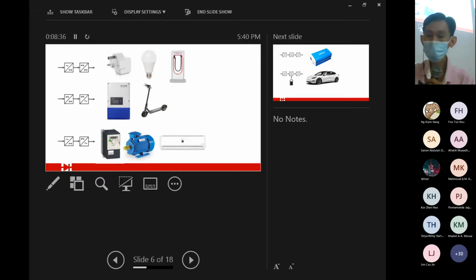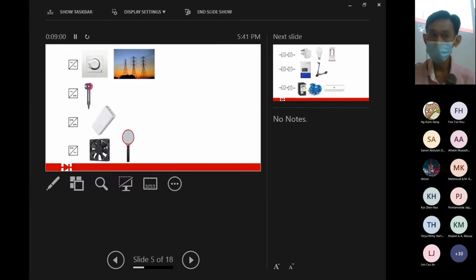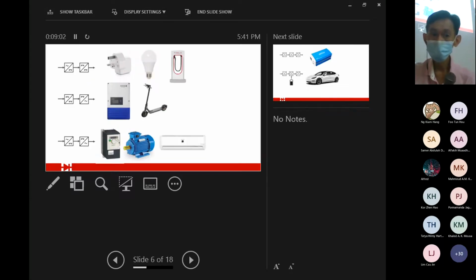Or our new aircon, the so-called inverter aircon. Now in the old days, our aircon is just AC to AC, that's all, to power the compressor. But it is not very efficient. So nowadays you will find the aircon says, I'm an inverter aircon, much more efficient, saves energy. So inside, instead of just using one AC, they put AC-DC, DC-AC. Then they can control the compressor better and more efficiently.